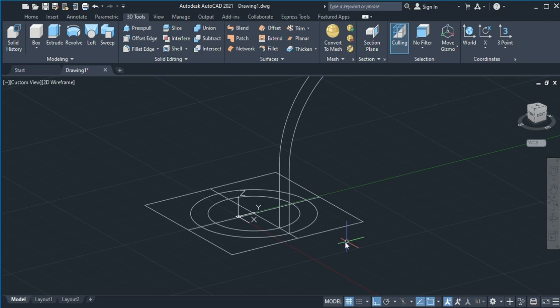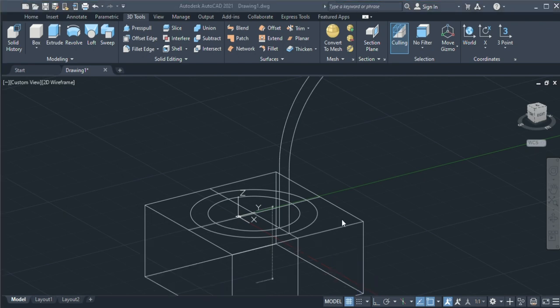Then join. So make it as a whole and then extrude. Since we already know that it needs to be extruded downward, if you extrude it upward it will add to the length of 150, right? So we need to extrude it to the bottom by the thickness, 50. Then later it's just identical.